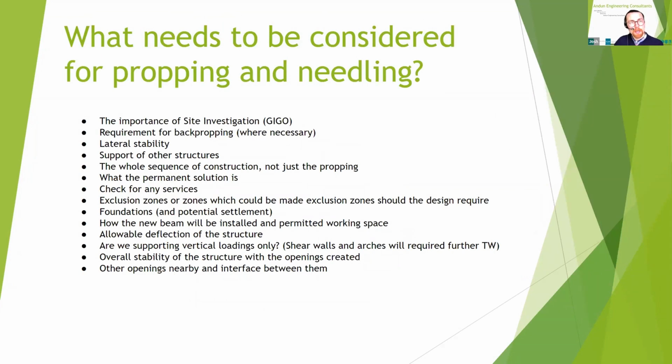So let's look at the type of things that will need to be considered when we're looking at propping and needling. Importance of site investigation. It's absolutely critical that we know what the structure is and how it's currently behaving so that we can predict what it's going to do when we start opening up and putting needles and props in. And it comes down to GIGO, which is garbage in, garbage out. If the idea of the solution is based on rubbish, garbage, then the solution itself is going to be rubbish. Proper site investigation is required, and a little thought and money spent at this stage will make for a much better solution, time in, time out.